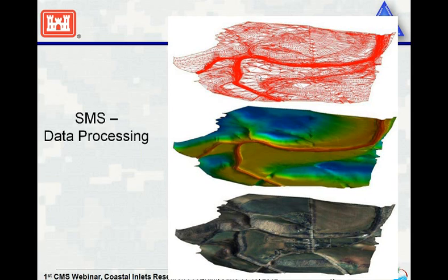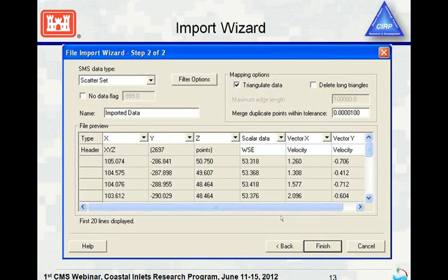So we work with bathymetry in the form of scatter points. So they're just triangulated points that bring in the information that you need. And that's the underlying way of getting the bathymetry into your grids.